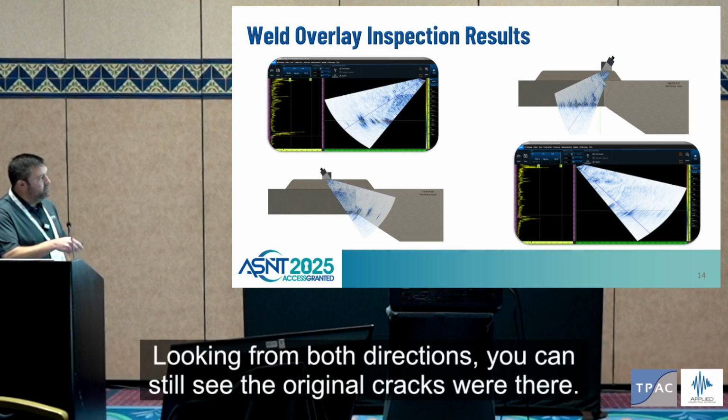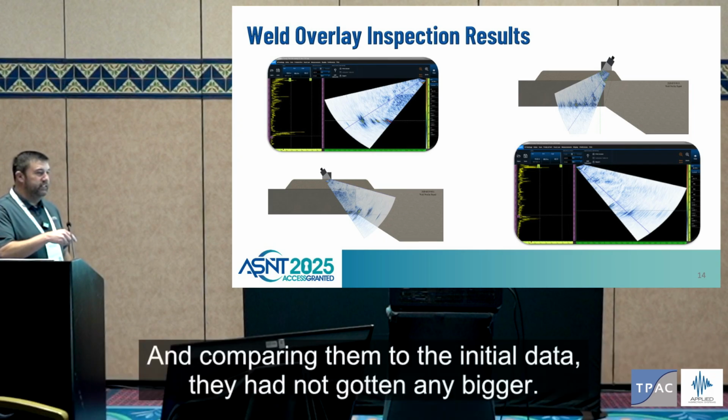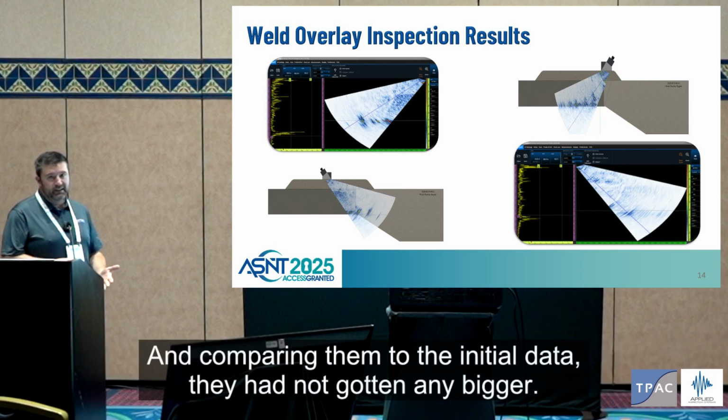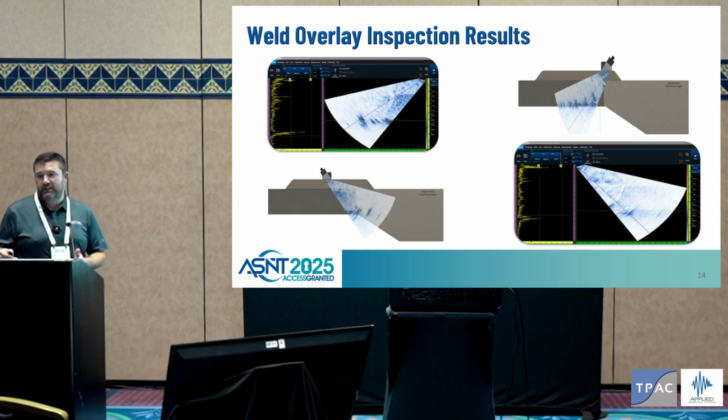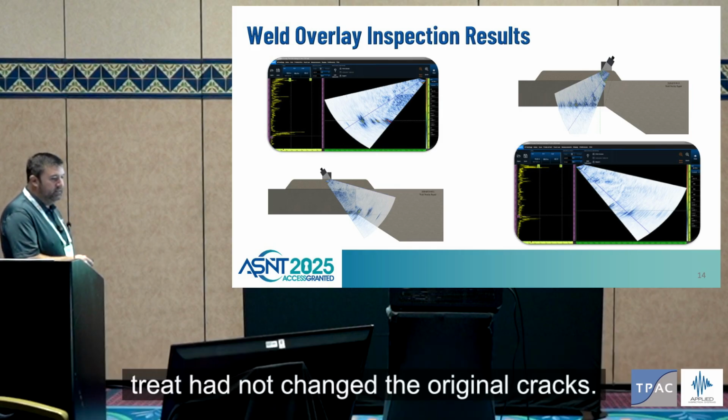Looking from both directions, you can still see the original cracks were there, and comparing them to the initial data, they had not gotten any bigger, so we were confident that the welding process and the post-weld heat treat had not changed the original cracks.